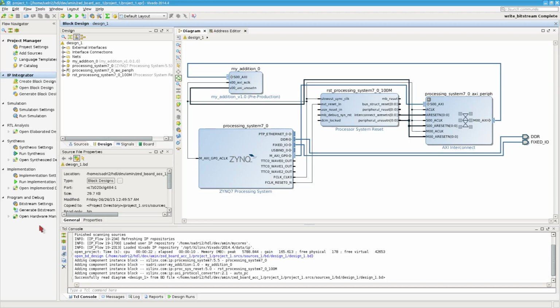In order to convert the Bitstream into a suitable format, which then can be used for being read out of the SD card and being used to program the PL, you need a kind of conversion step.